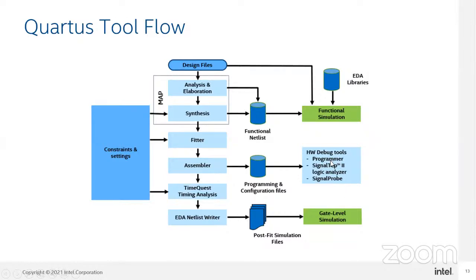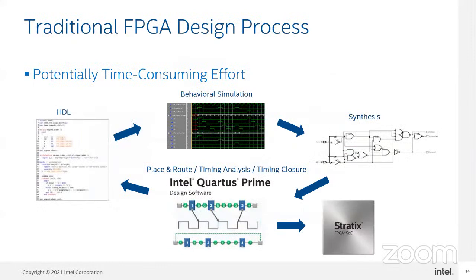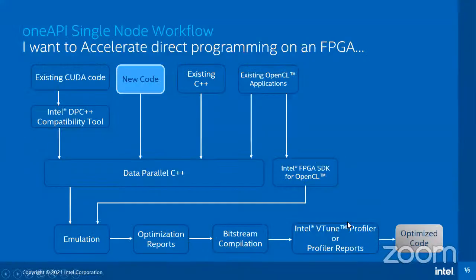Now what is our thought process? This is a potentially time-consuming effort, because you should write the code, perform behavioral simulation, do synthesis, then perform placement and routing, do timing analysis, then achieve timing closure and take the design to FPGA. But how do we solve this problem? That's what we are going to see now.